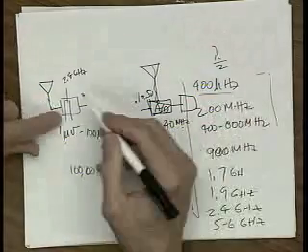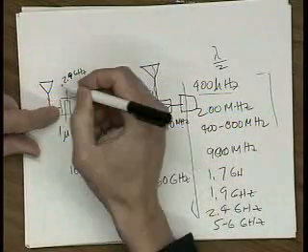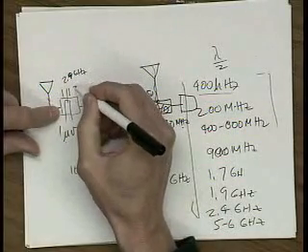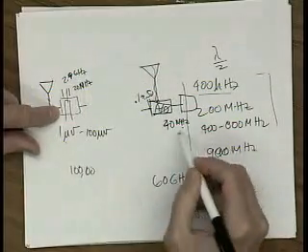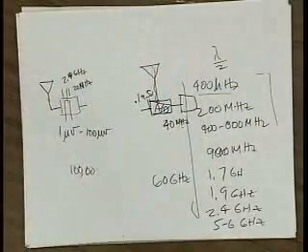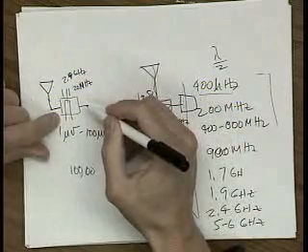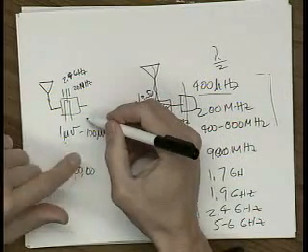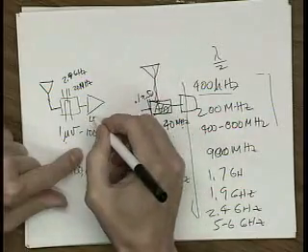And remember, the stuff's sitting up at 2.4 gigahertz. The width of the band of interest is about 20 megahertz or so. So it's 20 megahertz around 2.4 gigahertz. The first stage of a radio, what you do is you've got to get the signal bigger. So you go into an amplifier, a low noise amplifier.